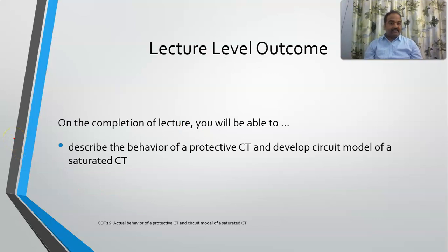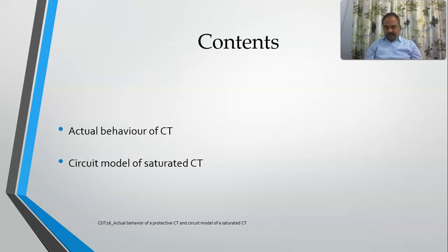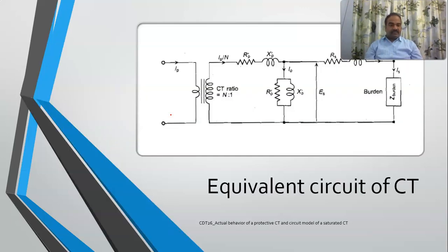So by the end of this lecture, I hope you will be able to describe the behavior of a protective CT and also develop a circuit model for a saturated CT, that is, how to represent the saturation in the equivalent circuit of a transformer. Now, I'll start with the basic CT, the equivalent circuit of a CT.